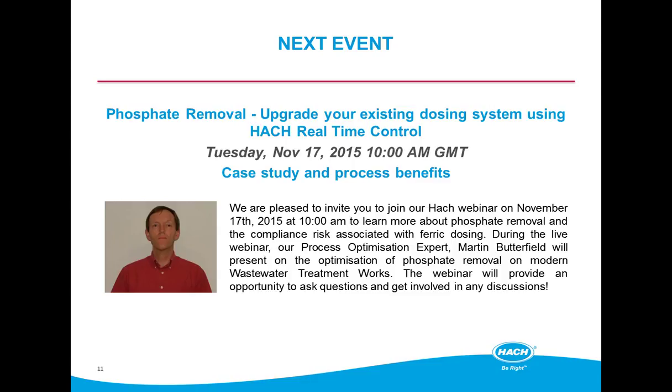No, because generally, as I mentioned in one of the early slides, the rate for BOD or COD removal is proportional to the actual load, that's almost self-leveling. So as BOD or COD increases, providing you've got an excess of dissolved oxygen, then the actual BOD or COD treatment rate will automatically increase.